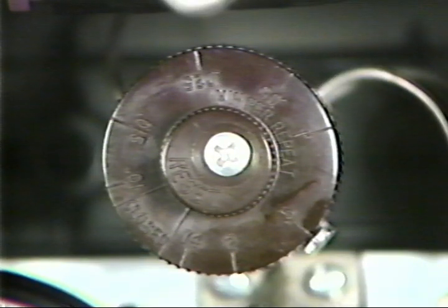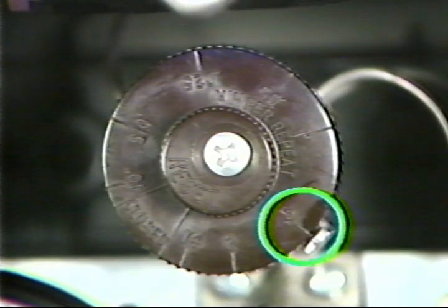This is the reset adjustment for the controller. It's adjusted to vary the output bleeding into the reset bellows. The units of measurement used on this controller are minutes per repeat, or the number of minutes it takes the controller to repeat its proportional output. So the 0.5 reading means that the controller will repeat its proportional output every half a minute.